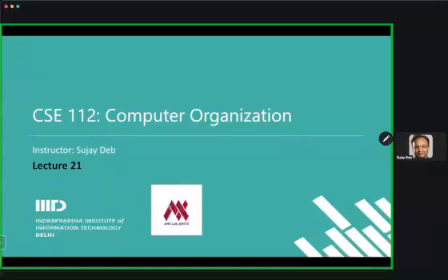So today, let's say I want to store a number which is 32-bit. I can have 32 flip-flops to store those numbers. And if I continuously want to store this number and don't want any change, every time the positive edge of the clock comes, I have to make sure that the data I want to store on those 32 flip-flops is the same. So that's how I can store this.